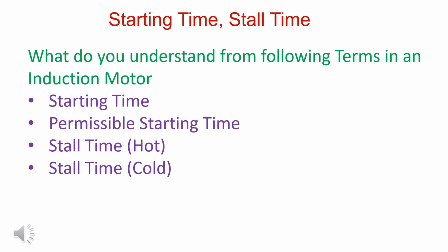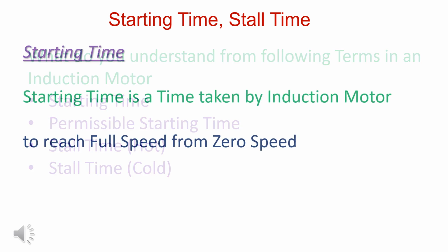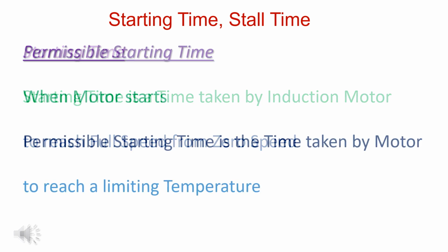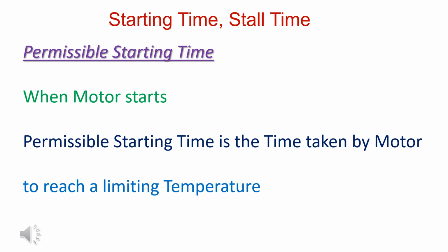What is meaning of starting time, permissible starting time, start time hot, and start time cold? Starting time is a time taken by motor to reach full speed from zero speed. Permissible starting time is a time taken by motor to reach limiting temperature after starting.